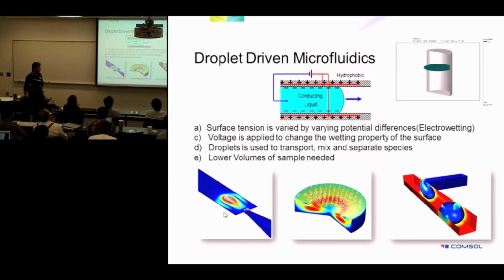This example talks about an inkjet printer. You will see in most inkjet printers that you have droplets of ink coming out from the nozzle, and then they're hitting the target. So this droplet can be formulated with respect to different physics available within the Microfluidics module, like the level set and the phase field methods.